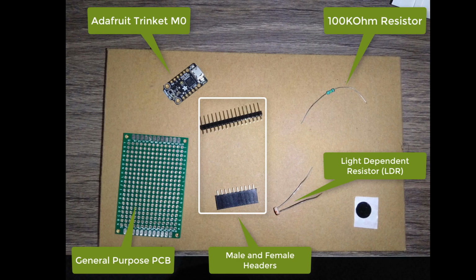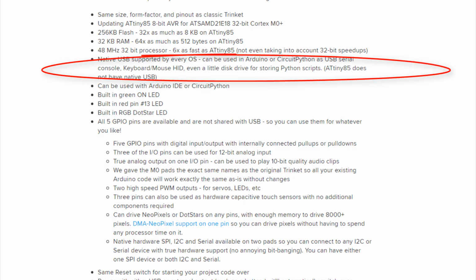Once you pick up the voltage difference arising because of the changing light intensity on the LDR, you need some kind of an action to be initiated on your PC or laptop. This has to be done through a device that supports HID. There are very few Arduino boards that support HID, and one among them is the Adafruit Trinket M0.